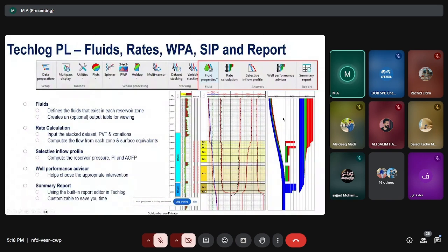I'm going to tell you each perforation, which is this perforation or the formations, how much is it producing and what the type of the fluid and what direction of it. So you can see here from this data that this perforation, it's producing only water, and this confirmed by having the density, by having the water hold up, by having also the other measurements, and it's matching here. So at the end you're going to have two curves, one that is the modeled, one the measured, and it should be overlaying or close to each other, okay, in order to have a good result for the rate calculations.